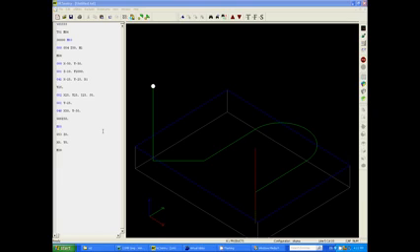Typically the two main information points that you need in your tool file for a particular tool is the radius of the cutter, so not the diameter of the cutter but the radius of the cutter that it actually cuts at, and also your height offset. So a lot of machines have probes and all this kind of stuff that you come down and touch, and that will give you a measurement to enter into your tool file, which will become your height offset.